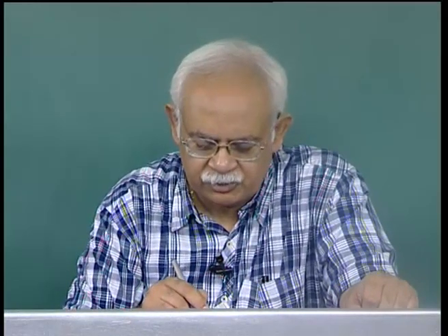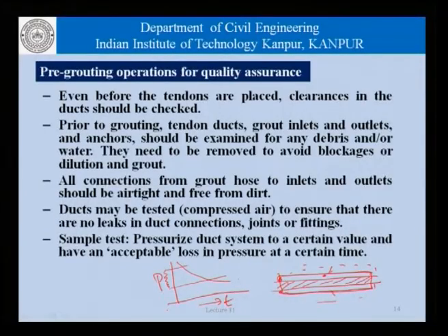Therefore, we carry out the test for a certain period of time, and the pressure drop during that time should not exceed a predetermined or acceptable level. So, this is how we can ensure an airtight duct system. It is not airtight in the scientific sense of the word, but it is airtight in an engineering sense of the word.